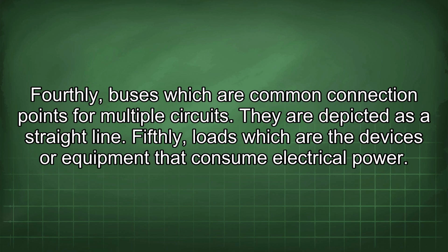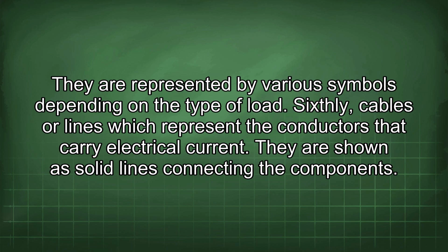Fourthly, buses, which are common connection points for multiple circuits. They are depicted as a straight line. Fifthly, loads, which are the devices or equipment that consume electrical power. They are represented by various symbols depending on the type of load. Sixthly, cables or lines, which represent the conductors that carry electrical current. They are shown as solid lines connecting the components.